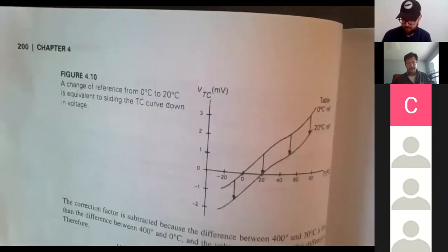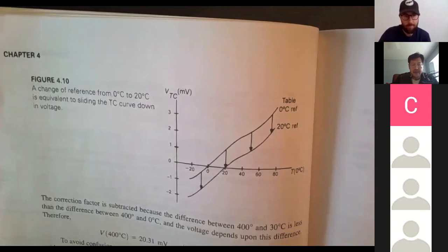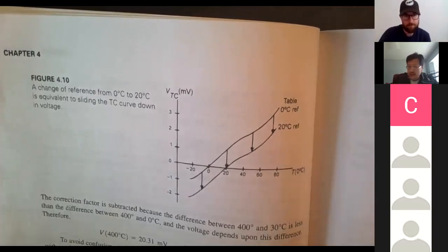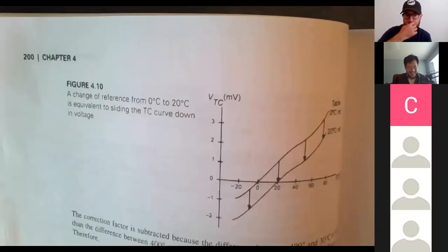Yes, perfect. The computer is so powerful. Now everything is done by computer. That digital correction is a perfect example. From what I understand from Joe's description, every sensor has its own characteristic. So you make a compensation for the different characteristic of a different sensor by a lookup table. So the computer will basically look up a pre-existing table, pre-plotted with the characteristic of your sensor, and make corrections for the variations. Is that right, Joe? Yeah, that's exactly it right there.